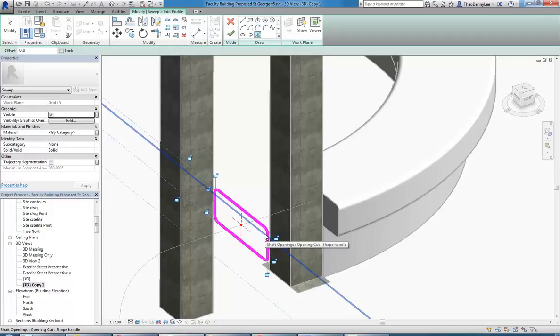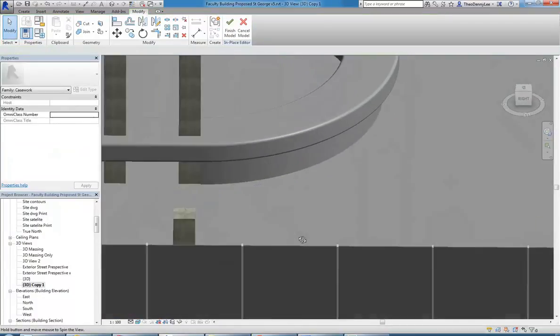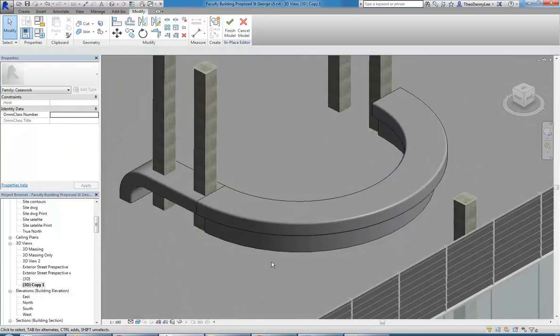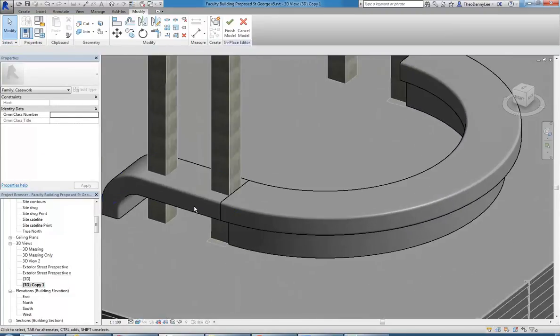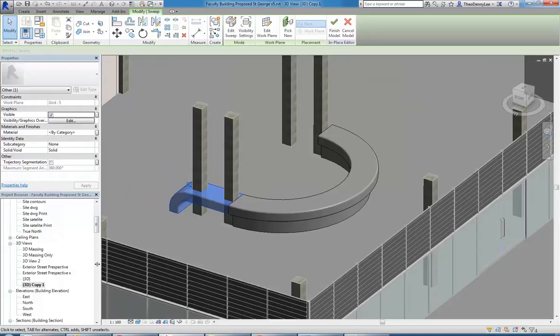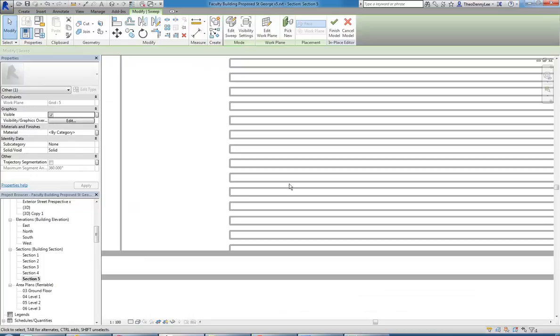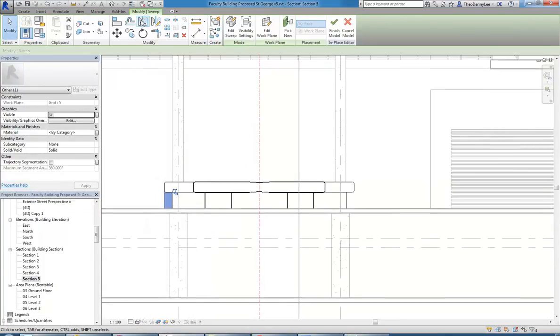And this is one of the best things Revit does, projecting in 3D as you draw different 2D shapes. It's a really useful technique that Revit always does really well. So that's it. Tick to finish. Tick again. And that's made my shape. Okay, so then I can mirror that across to the opposite side, simply going into my section view and using mirror pick axis.